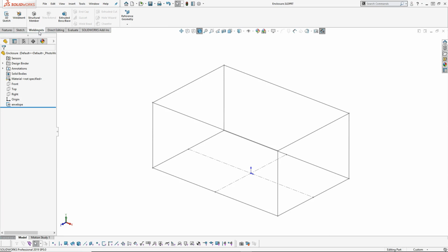It's time to check. One of the other things is that I built this to the outside, and I need to think about the overlap, because there's a few things that I can do with the trims and how I want to manage these edges. If I do the L shape around the top, and then the L shape will trim those out. One of the other things that I could do is split or break these lines a half inch down, and it would only extend, so it would save me a little bit on the trim. So we'll put the mitered frame in first, and then we'll take a look at what it would take to split those out and what happens as we go.